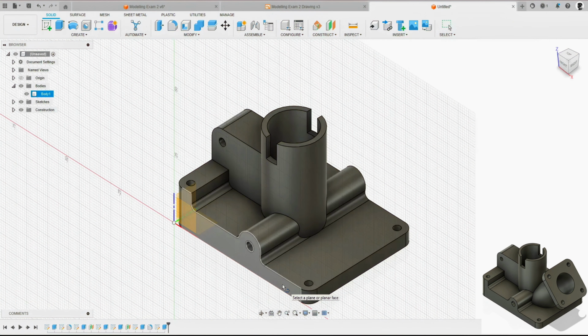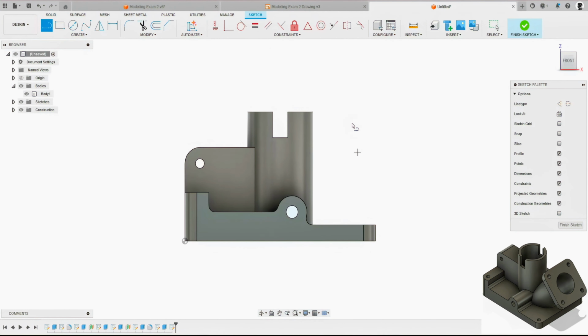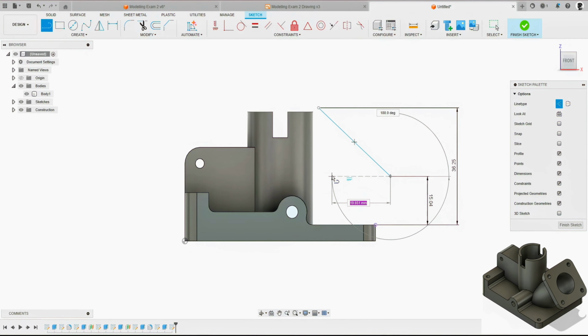Let's use the line tool then, and let's do a sketch on this plane here. Use the line tool then, let's draw down a line, something like that. We must dimension this point to this point, and that is 15.04. And this point to this one here, we've got 36.25. We know this line is at a 45-degree angle, so let's hit another line, meet that construction. Draw this with a horizontal constraint, just D on the keyboard, dimension these guys, let's go 45.